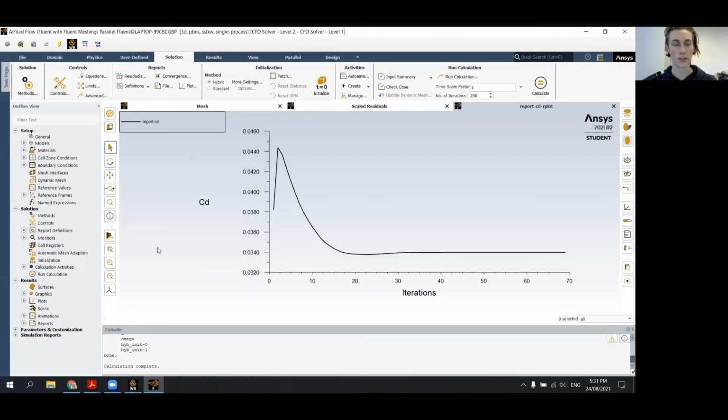Now, is that because our velocity is too low? Should we try it with a high velocity? You know, think about these kinds of variables before you run with your solution. Do we need to refine our mesh further, closer to our nose, to the body? What's going on? So try a couple of things and see what different values you get. But this is definitely closer now that we added the roughness.